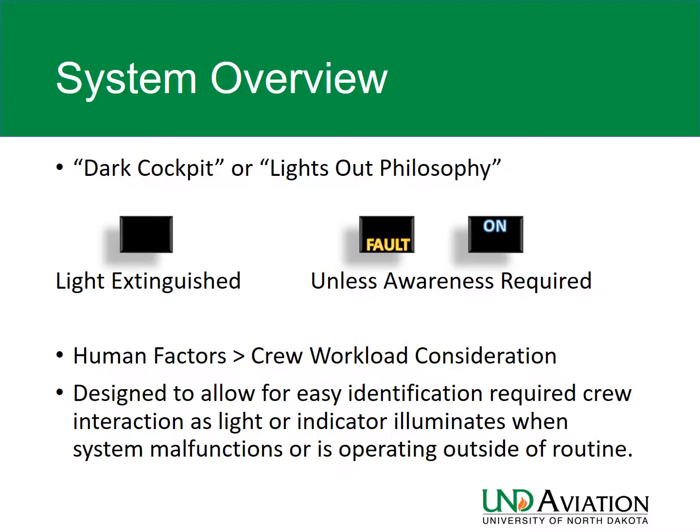The idea here is when you're looking at your displays, or looking in and around the aircraft at how we receive information, one of the thoughts is, if you don't need the information, or if it's in an automatic mode, or if it's working normally, let's keep the light extinguished. If there is some sort of abnormality, then illuminate it to the crew.